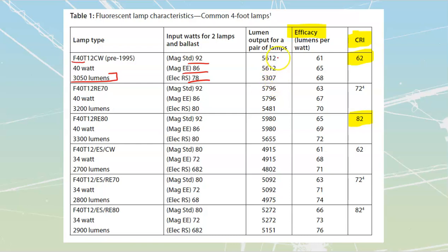So these ones over here are going to have different values. You'll note that the higher up in lumens I get, the worse my CRI is going to be. Generally, the higher up we get, the more towards the blue range the light color is established, because all of your blue lights are super high frequency. Your red lights are lower values of frequency. So those lower values are going to be seen as slightly more natural, right? Outside light is generally considered to be a warm type of light.